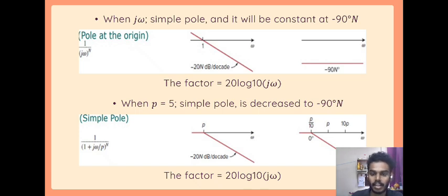The double pole at omega equals 5 is more complex, being squared, so n equals 2. Its phase contribution ranges from 0 at low frequency through negative 90 at omega equals 5, to negative 180 at the highest frequency, because since we have negative 45, we have to multiply by 2. This table confirms that the poles create phase lag, with the final multiplying by n for repeated poles.